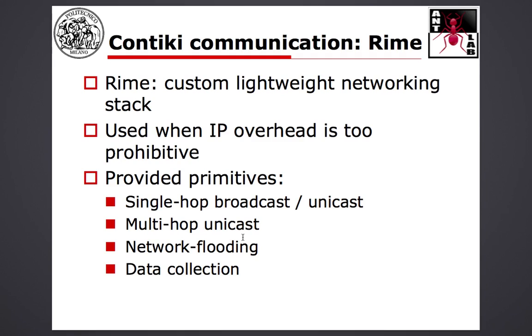It also provides some primitives for network flooding, meaning disseminating data from a central point to all the nodes. This is called flooding. And also the reverse process, which is data collection, so from all the nodes to a central point. So with RIME, you have already implemented these two very useful primitives, and that's why I guess you find Contiki as a starting point for many commercial applications.